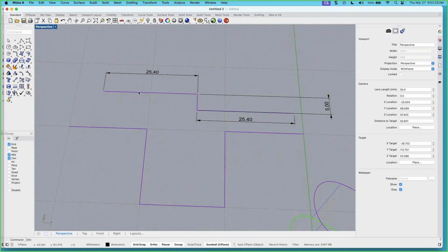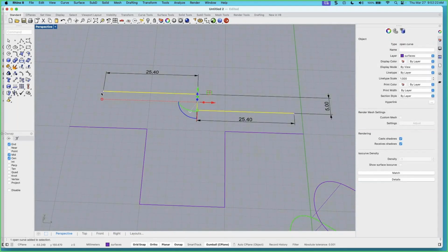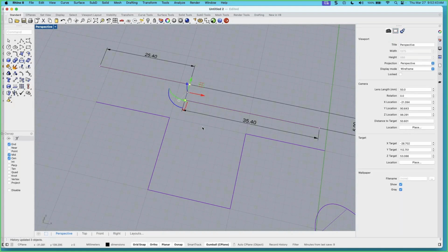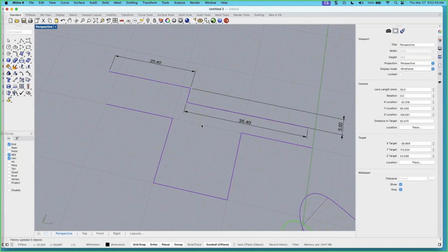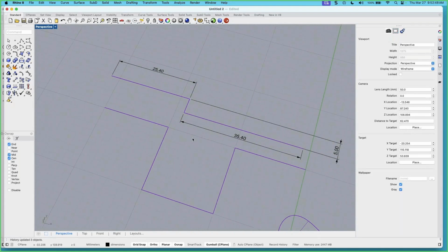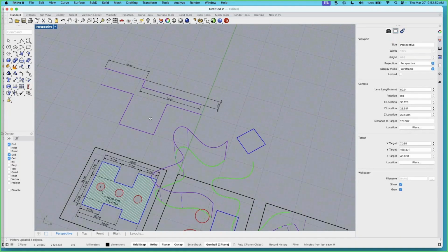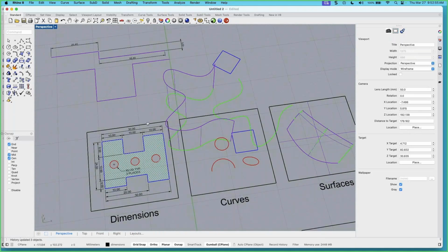Okay, so what if I wanted to change this distance? This is where the control points come in. So I can type in this case, it's a -10. And when I move it -10, the dimension updates. So once I get that dimension, I begin to really be able to dial in the distances that I'm drawing to, and get tangible proof that what I'm ending up with is at the proper scale.